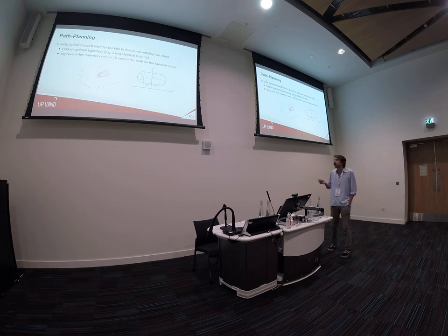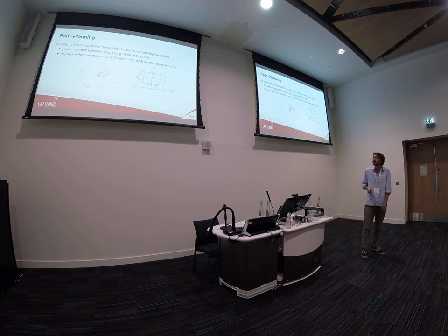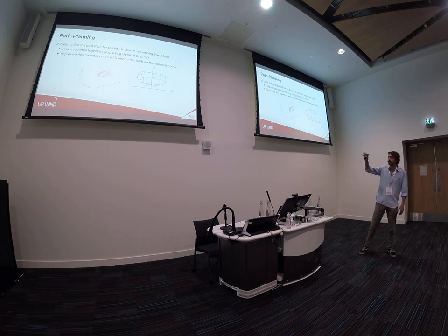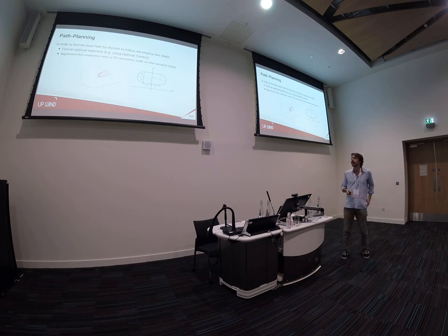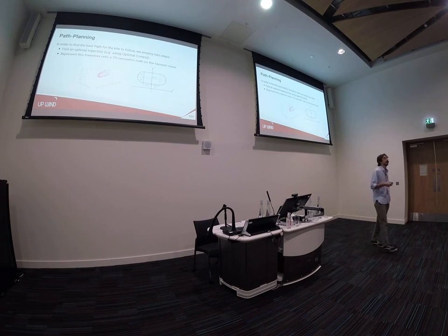But we've been using a kind of optimal control in a first approach, and then we transfer the resultant trajectory onto a 2D plane, a tangent plane to this spherical surface. The spherical surface is defined by a center that's the ground station, and it has a radius equal to the tether length. So we're assuming there's no elasticity. As an example, I'm going to use this kind of elliptical shape path.